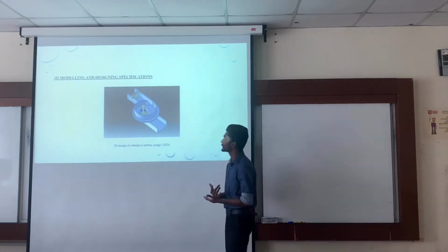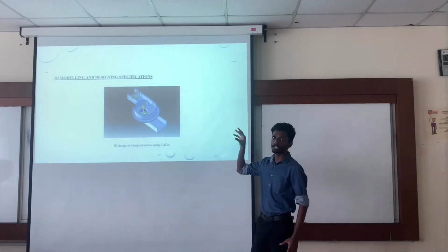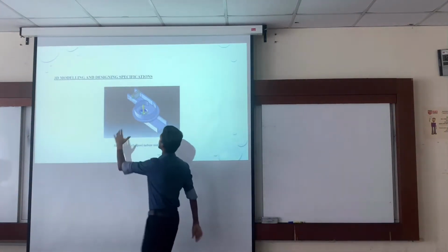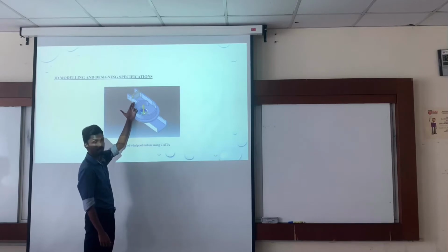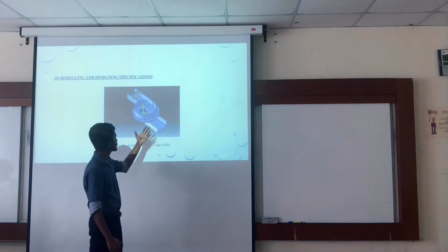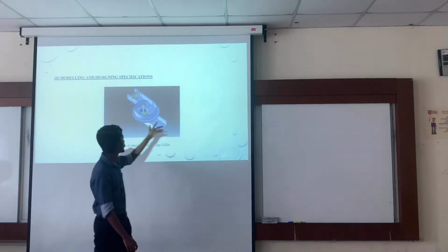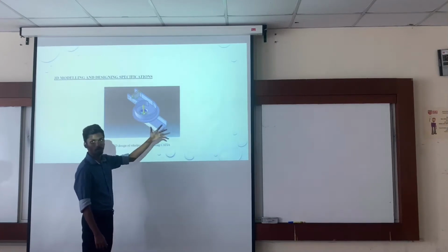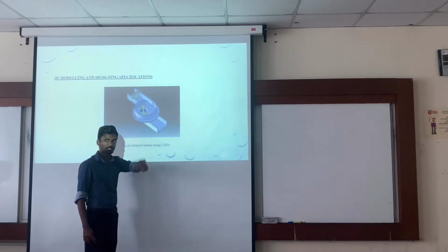As you can see from here, the design is quite unique. The basin is designed in a way to create a whirlpool. Let me explain part by part. Firstly, as the water enters, you can see there's an automatic slide gate. The function of this slide gate is to control the flow of the water. As you can see, there's a limited amount of area for the water. If too much water is inside the basin, the water would overflow and the vortex cannot be created to move the turbine. So that's the reason for this automated gate.